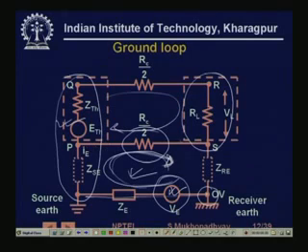So, these ground loop currents can cause potentials here, especially if you are making single ended measurements. Whenever you talk of a voltage, it is actually between 2 points, but sometimes we assume that one of them is some standard common reference voltage of the whole electronic circuit. Whenever this assumption is reasonably good, we can just take one of the wires and connect it to the circuit and assume that the other is the common ground of the circuit. Such measurements are called single ended measurements.